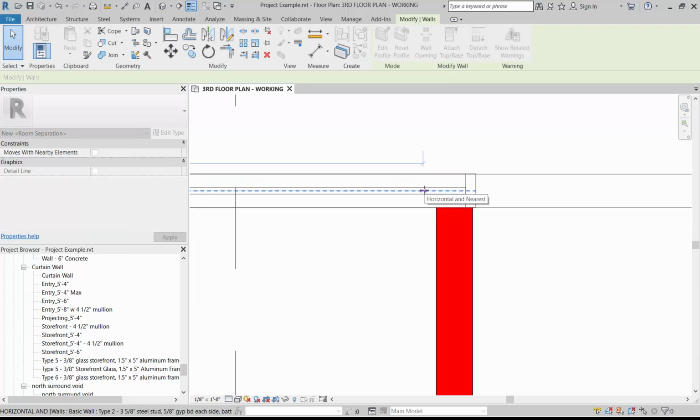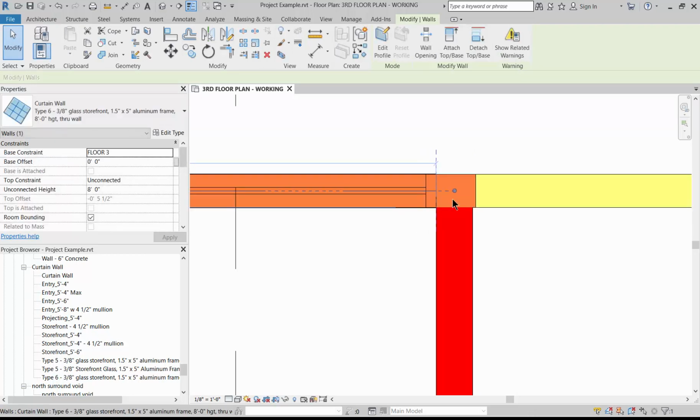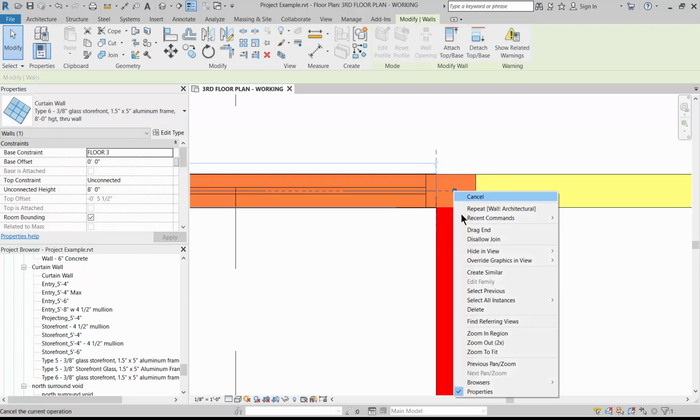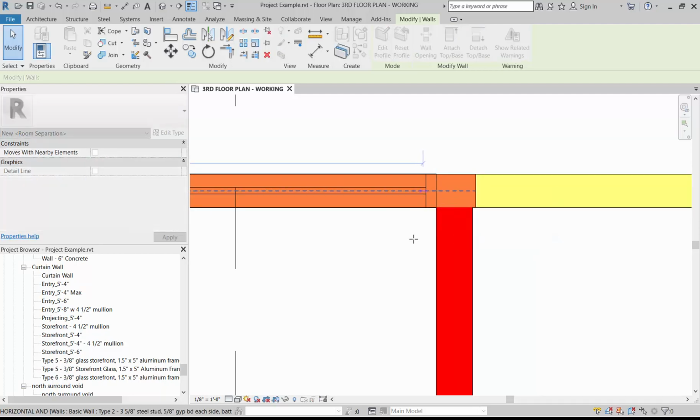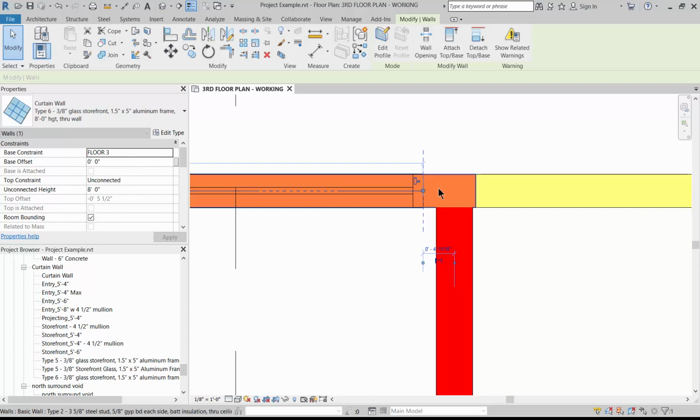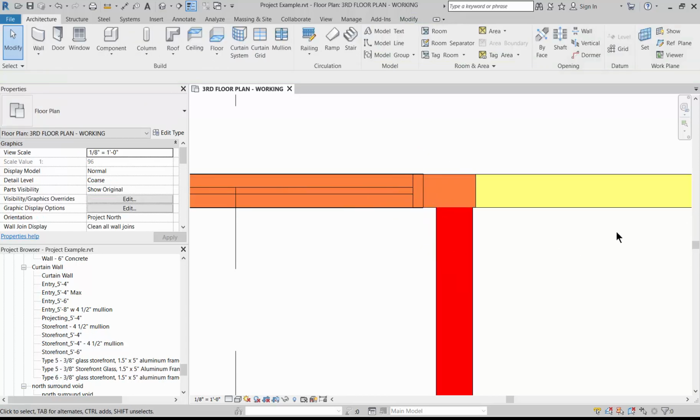You always want to stop just inside of the edge. And by disallowing join here, you can actually draw it in a couple of inches to allow space for a stud for the framing to happen on this corner. This is something you can clean up later on, but again, as everything else, it's good to do it as you're going along here.